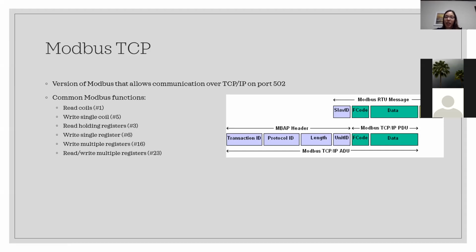You can't communicate that back from the PLC to your engineering workstation or your HMI that you're using to monitor the process. Suddenly you've got a 30 millisecond delay or 40 millisecond delay. While that seems very small, in an industrial control system, that delay is often unacceptable.